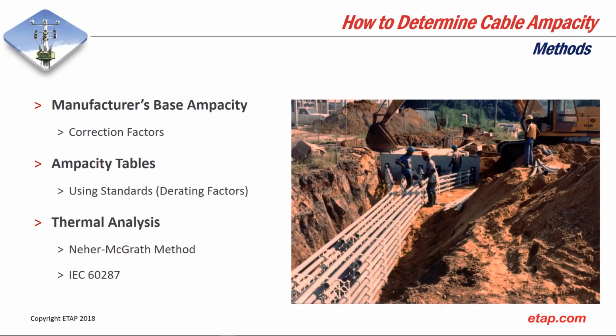Also the ampacity tables using standards and the rating factors. This is more for NEC and ICEA P-54-440 standard, where the standard typically provides us with ampacity tables, also with installation tables, so we can go there and look it up. Also, and this is not part of this presentation, thermal analysis using the Neher-McGrath method, or IEC 60287, can also be performed to come up with a thermal analysis to squeeze the most performance out of our cable installations.